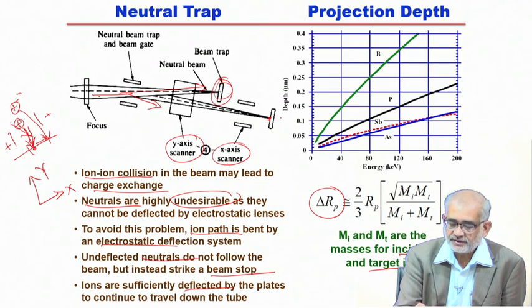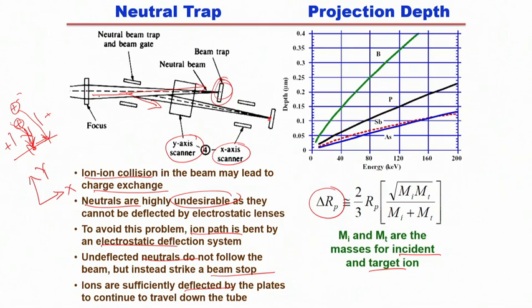Now, we already saw, and this is again very clearly shown, that whether it's arsenic or antimony or phosphorus or bismuth, whatever species you want to implant, in all the cases the depth to which they penetrate is directly related to the energy. So as you increase the excitation energy from say 30-40 keV to 160-200 keV, the depth to which you penetrate will be greater, and that allows us to control the depth of penetration precisely up to the extent we want.